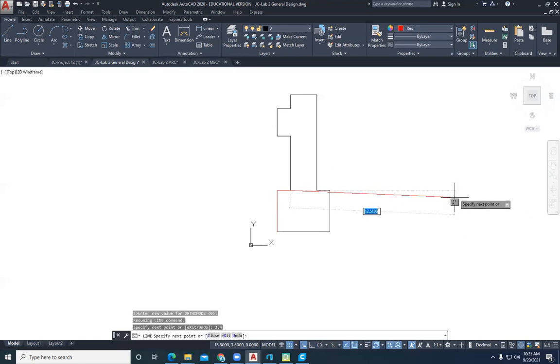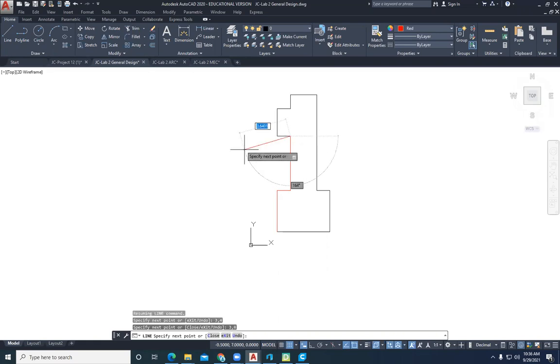And you can see that it's following the outline. Now, there wouldn't be an outline there if I didn't have one, but since I do, I'm just going through what's called absolute coordinate entry. And so if I go to the next point, I'd say pound 3, 8. And that would be 3 units over in the x-axis and 8 units up in the y-axis. And so essentially, we're learning how to use these absolute coordinates.